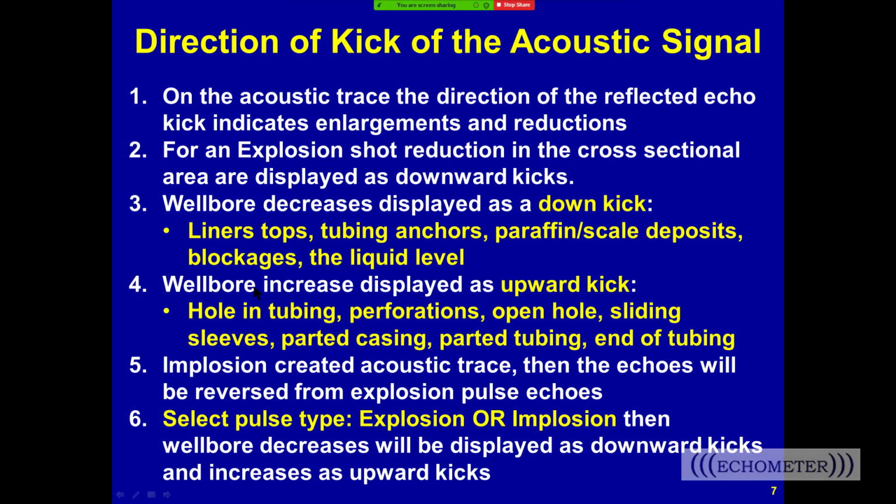Now, when the wellbore gets larger and echoes are displayed as an upkick, those could be holes in tubing, perforations, open hole, or a sliding sleeve that could be open. A sliding sleeve that is closed may not make an echo. Parted casing, which you would not want, or parted tubing, which you would not want. And if you have a liquid level below the end of tubing, you'll see an upkick at the end of the tubing.